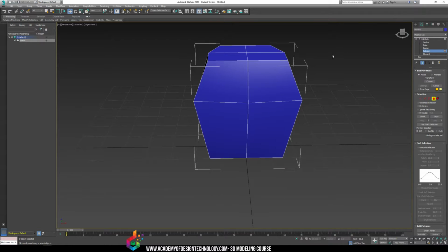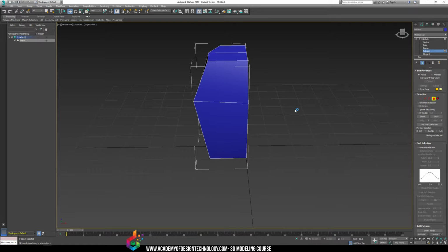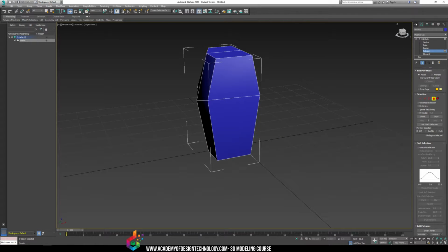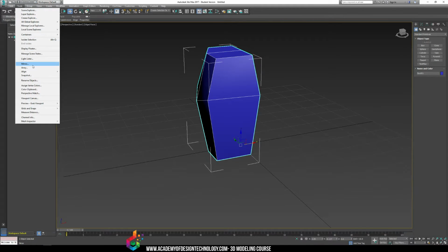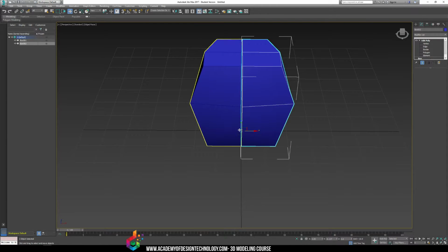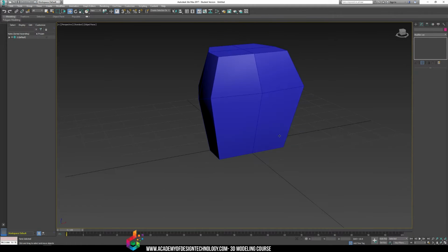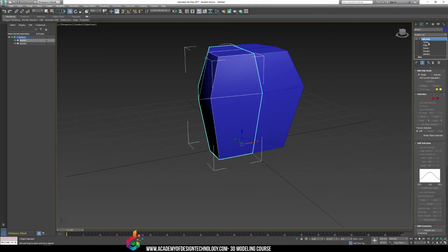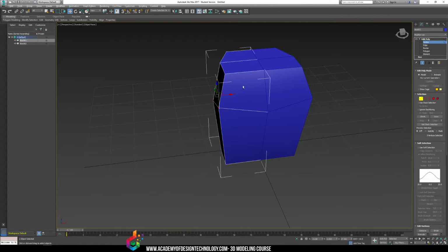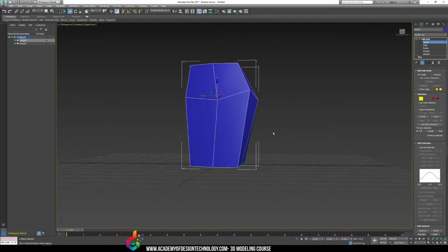So to do that, I'm actually going to delete half my chest model. And now I'm left with an open hole and only half a chest. Now I'm going to go to Tools, and I'm going to go to Mirror, and it's going to create Transform Mirror on the X, which is left and right, and it's going to create a reference. Luckily enough, our pivot point was right in the middle of our object, and it referenced exactly symmetrically for us to use. So now if I modify one part of the object, I just have to grab the vertexes or polygons or edges on the left side, and it will automatically do the same thing on the right side.